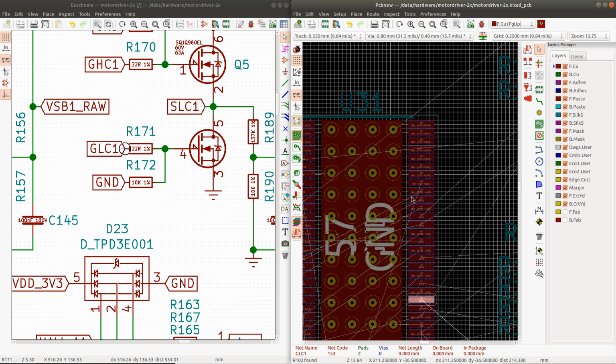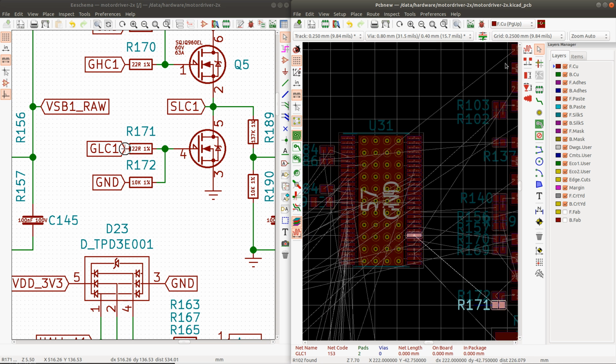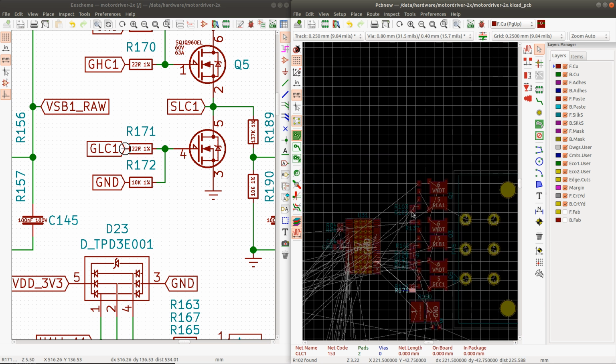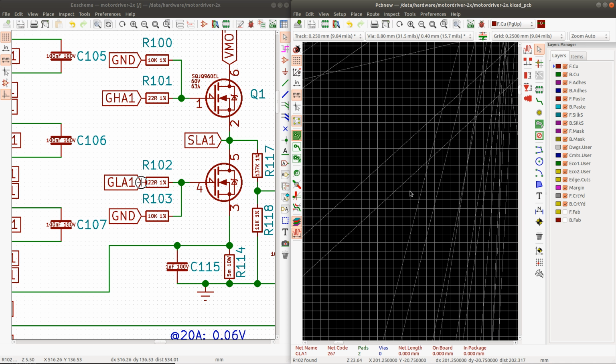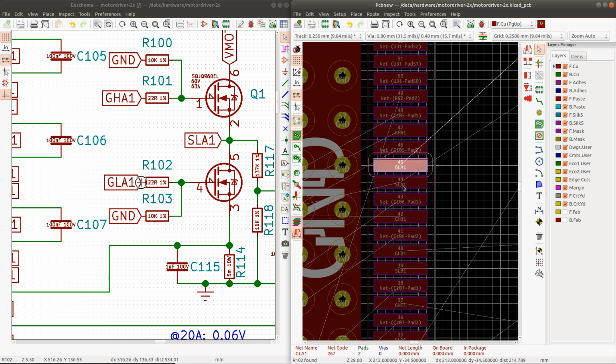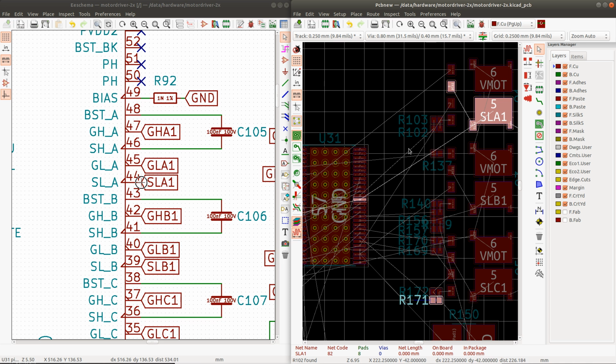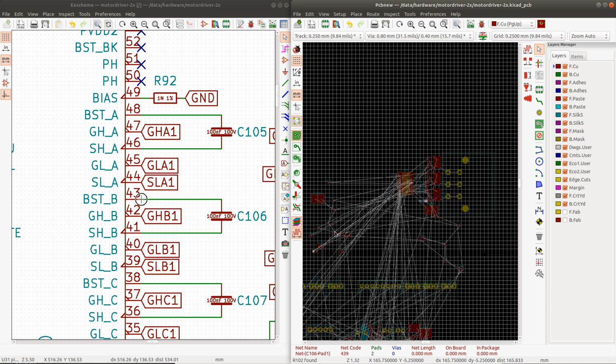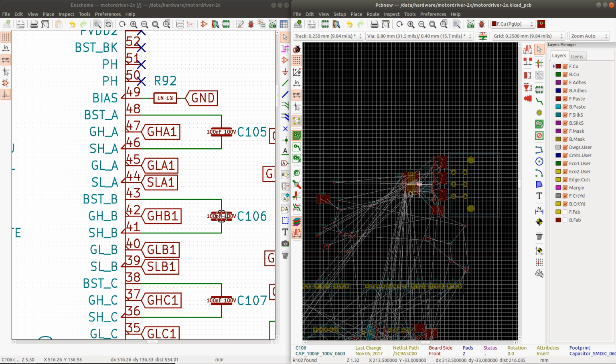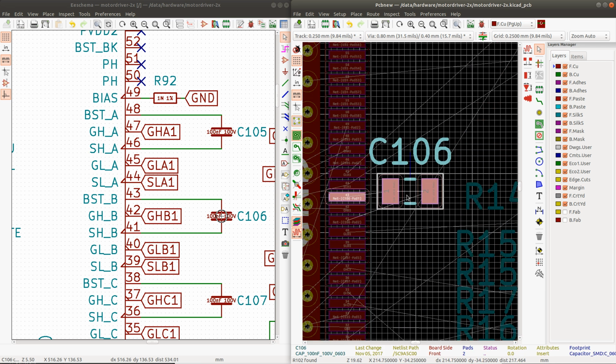Okay. So just looking, I can actually go like this. I can start with the top one, and then I can look at every single signal that comes after it. So these two will ultimately route in this direction and directly connect. So that's fine. But then we have this one. It's connected to a capacitor. So we can move this capacitor in place as well. And it's essentially just a capacitor that will be routed like this.